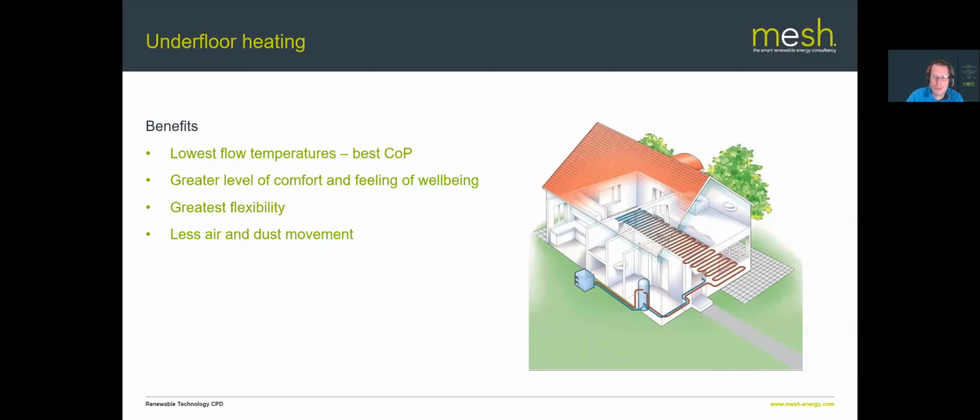Also, underfloor heating works very well with flooring that could be considered cold without underfloor heating, so things like ceramic tiles, that kind of thing. And again, those are less likely to trap dust and dirt than, say, carpets are. So it can be good from that point of view. And it's compatible with most floor finishes. Just obviously a little bit of care when you're using a floor as a heat emitter. If you start putting great big thick highly insulated carpets over the top of it, oddly enough, it tends to keep the heat in the floor rather than letting it out into the room.